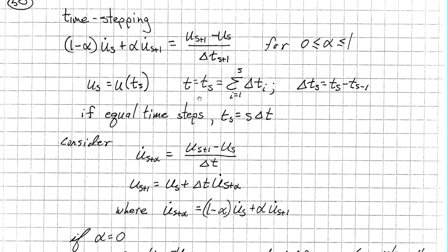Now we're really getting into transient problems. So here is a case where you have a nodal solution, let's just say for now displacement. So you have displacement of future time step minus current time step over a delta t increment in time. And that's equal to the following weights of the velocities based on whatever alpha is. Alpha may be anything between 0 and 1.